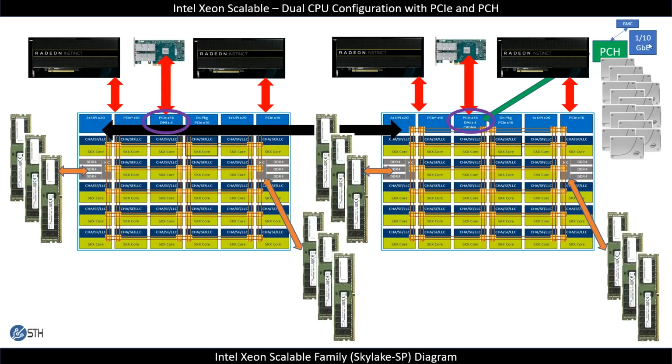On the other hand, you get 10 gig networking, and there are some things that you need in a server, such as a BMC, which also will sit off of PCIe. Usually you put these onto lower performance PCIe lanes. So in this generation, you can hang your BMC off your PCH PCIe lanes, and therefore you can use 4 lanes on the die, but actually get a lot of connectivity.